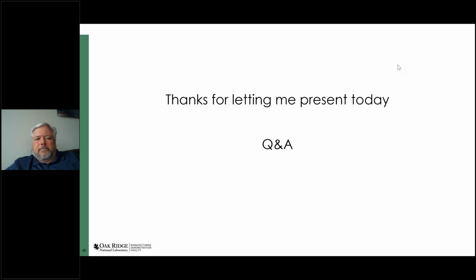And I had one more question. I'm sorry, Scott. Does your rake angle have an effect on the chip break at all? So, certainly the rake angle has an effect on whether or not chips break. And that's always true. But as far as whether or not this will work, no. Because this one works because the tool actually literally loses contact with the workpiece. The chip thickness goes to 0 because of what the axes did. Okay. Thank you.